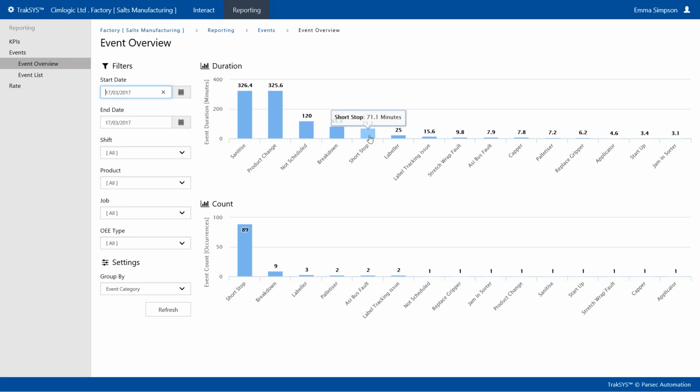And if we have all this time, eventually we might find that if we had a buffer on the filler, we might be using the filler at maximum capacity, and we could have an hour extra of uptime for this line. So these are the type of conclusions that we might take from the downtime analysis of a line.